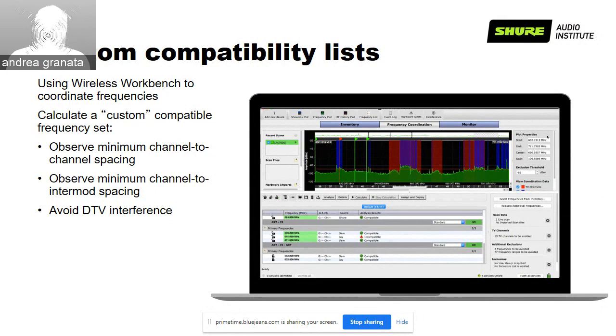An example is if I have a big ramp and the singer I know sings a lot 40, 50, 60 meters away from the antennas, I want to make sure that I still have enough headroom at that point for when the audience will be inside. During my sound check, obviously everything is fine, but I'm not just happy that everything is fine. I want everything to be absolutely fine and to have some headroom to play with for the moment when I see the noise floor increasing. So all you can do is your homework as well as you can to prevent the noise floor from disturbing you.